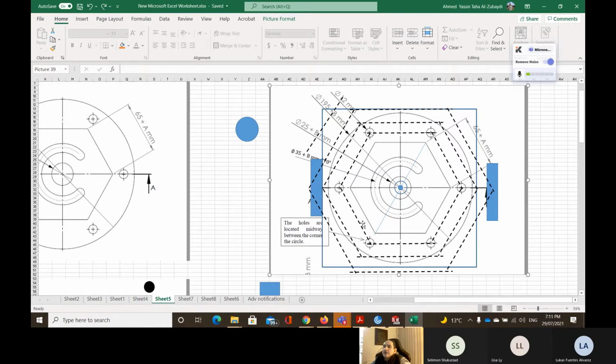Again, to make the tool path attached to the final cut, we offset by a value equal to the radius of the cutting tool. And of course, this is only going to cut around the shape. But we still have a cubic shape, and we need to remove the material from the outside to the inside to have the final shape. So we may have multiple offsets until we get the final one.